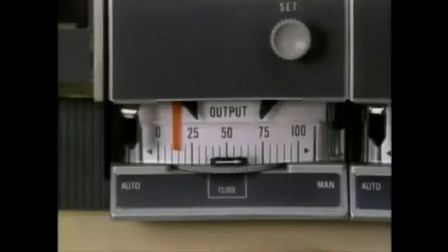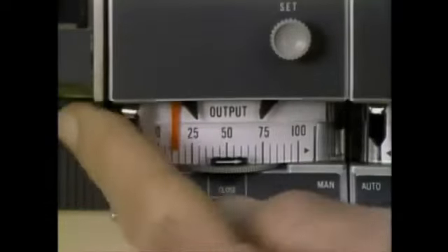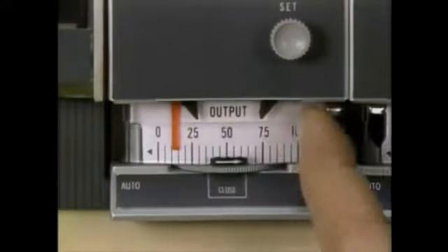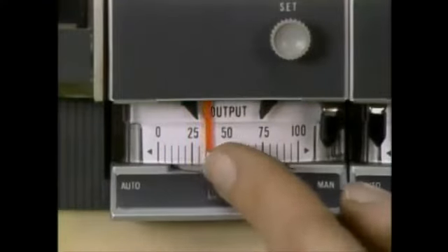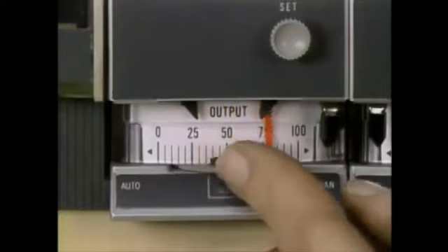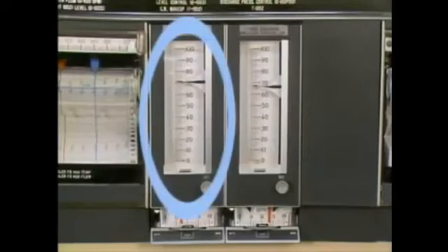When a system is not operating in a normal mode, an operator may need to take direct manual control of a process variable. In manual control, the operator sets the controller output signal directly by using the thumb wheel to adjust the position of the final control element as indicated on the horizontal scale. After the controller output is set, it will remain constant. This keeps the final control element in the same position until the setting is changed by the operator or until the controller is set to automatic operation. For example, this controller can be switched to manual operation at any time.